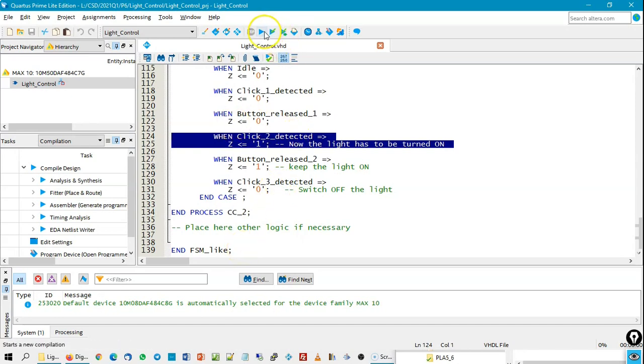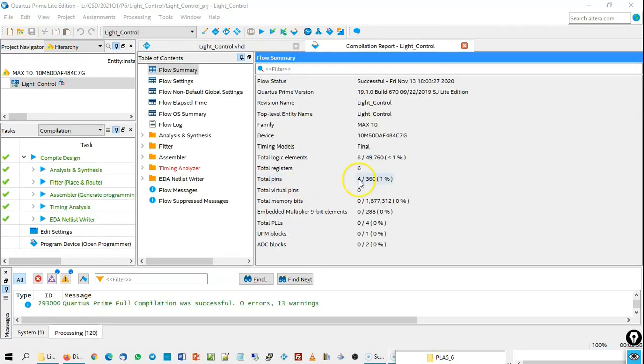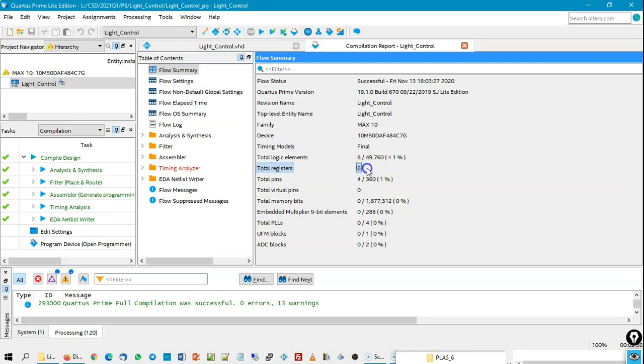So now it's time for running the synthesis process. If the process finalizes correctly, you see that in the end you have, for example, total registers 6, because probably the machine, since you have not said anything special, has adjusted to the best method that it can find. For example, this time the machine is using 6 register flip-flops, this means that it's using, guess it, right? One hot internal coding style for every one of the finite state machine states.